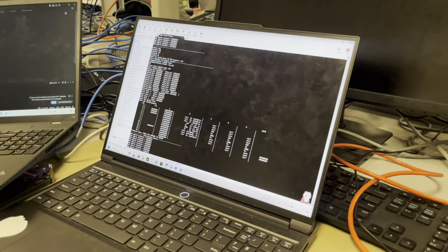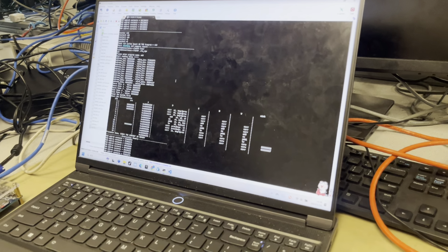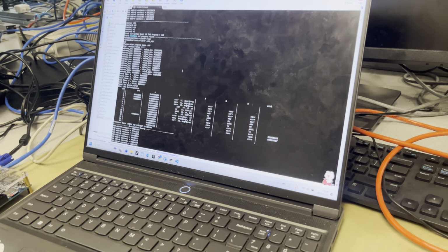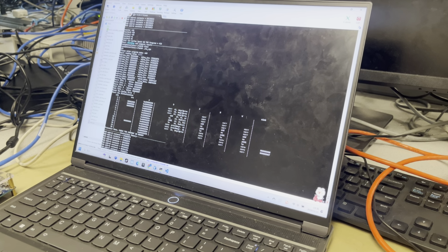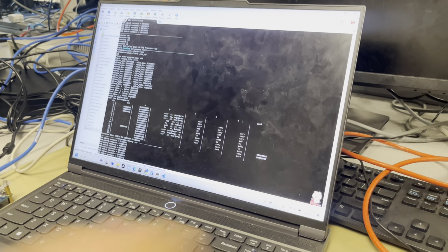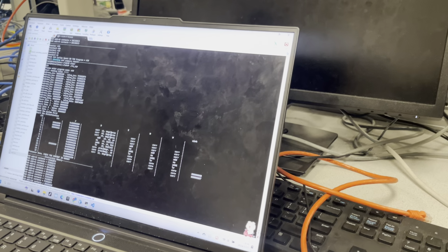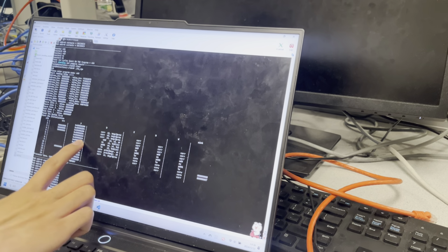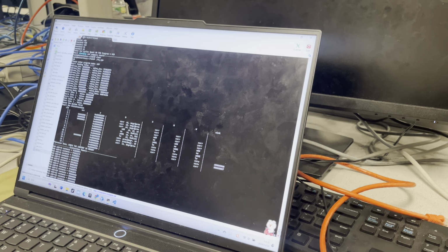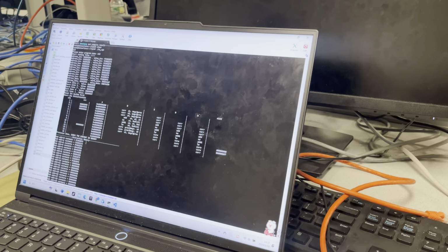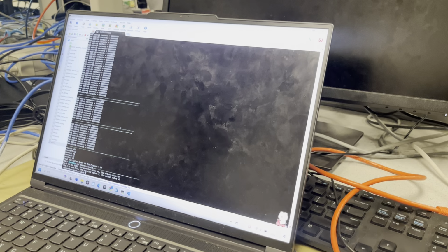On the ARM side, at first it starts reading the hex files and starts the initialization of the instruction memory, the data memory, the sink memory, and the source memory. And then it will print out the line trace of the whole processing procedure of each stage on the processor in each cycle. When the processor is done, it will dump all the memory to check the content to see if it matches our expectation.